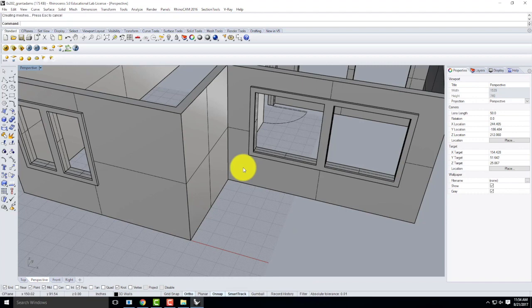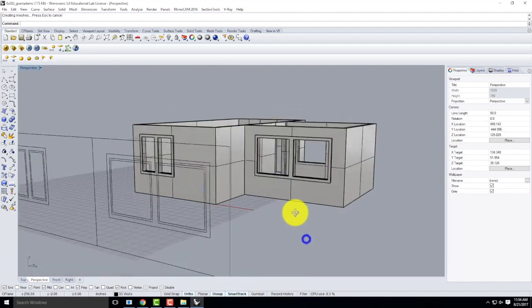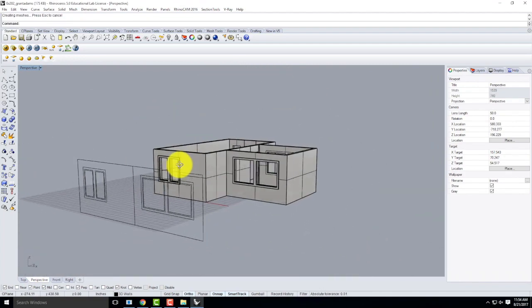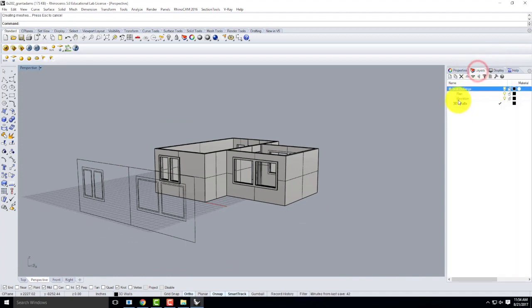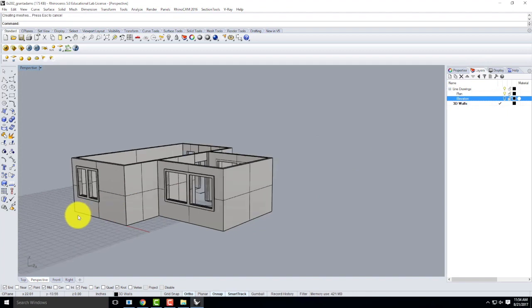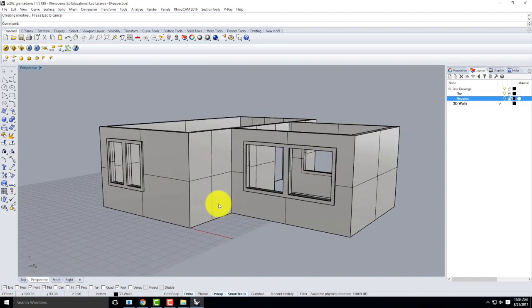The key thing today is understanding rotate 3D, understanding extrude, and understanding project. If you get those three things down, I'm very, very happy. When you're done today, set yourself up with a reasonably nice view, something like that. Remember, you can turn off the elevation if you don't want it anymore. Let me turn that off and make that a little bit bigger.